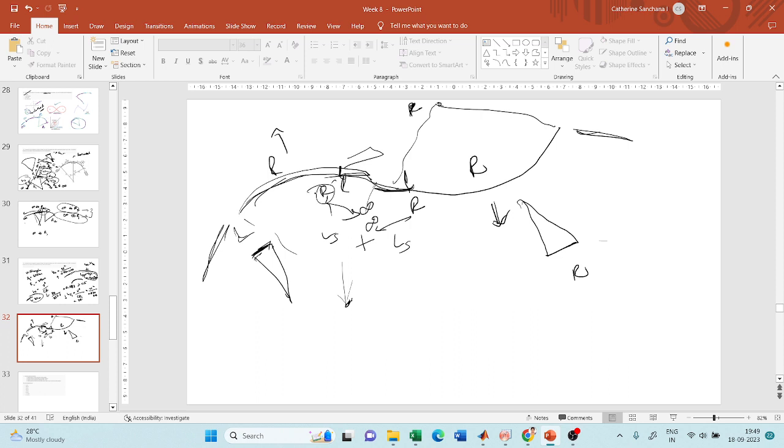Because here the super elevation is in one direction, and here the super elevation is in the other direction. So for you to reduce the super elevation from one direction to zero, and then raise it in the other direction, right? So it is just like doing it for a normal horizontal curve.